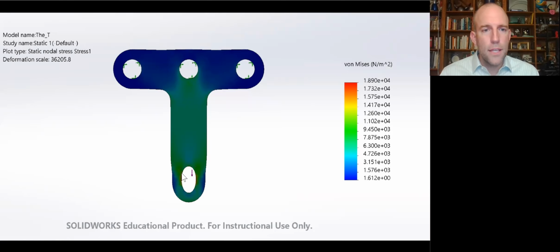And this picture looks a lot like that left-hand case, where we just have the reaction force at the center hole. All the stress you can see is being reacted out in the center hole. Well, what if we fix it with bearings instead of fixing the inside of the holes? We'll get into some of these things again when we talk about FEA. You get a very similar result. It's true there's a little bit of bending happening up here, but almost all the force is going towards that center hole.